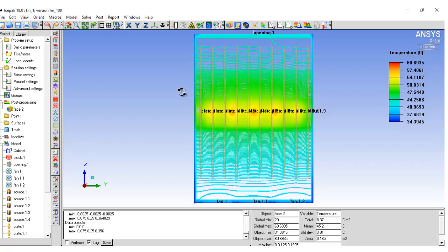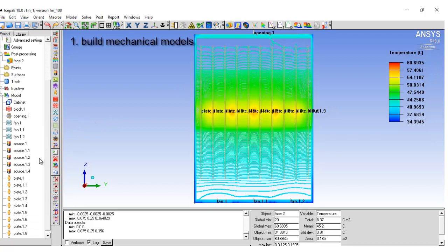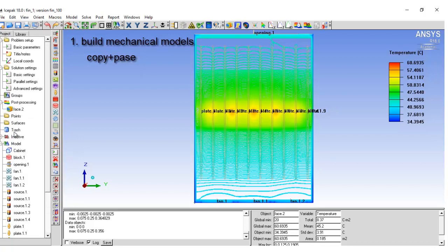In the first example, we introduced how to build the blocks, how to use the sources and the plane, and build the fence. The most important method for you is copy and paste. You don't need to build everything using blocks, and that could be very slow. After the mechanical blocks, I taught you how to do the mesh and generate the meshing. And after you generate the mesh, you have to show the mesh inside your model to check what you want to observe.